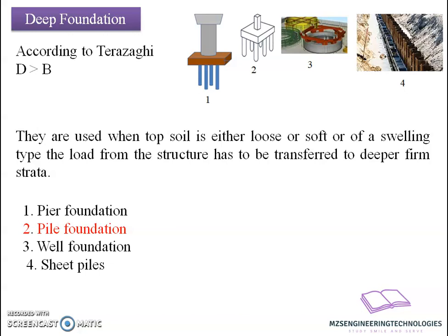If the depth of the foundation is less than or equal to the width of the foundation, we are going to call it a shallow foundation, whereas if it is greater than the width of the foundation, we call that a deep foundation. But the actual concern, when we look at the function of a foundation, is to transfer the load from the structure safely to the ground without excessive settlement or failure.